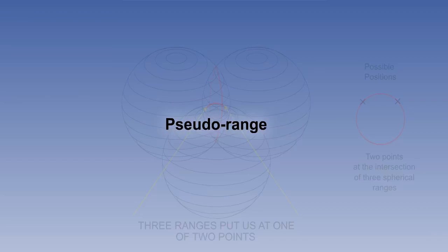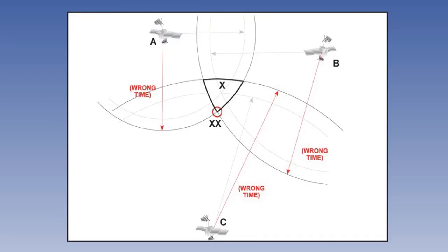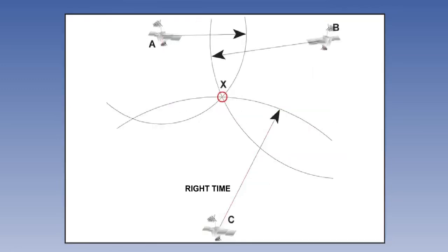This desynchronization, or clock bias, means that the range calculation will be erroneous, which is why it is referred to as a pseudo-range. The receiver clock is deliberately kept in error by a small factor to ensure that the correction process can only go in one direction. As a result, the position lines will not meet in a point, but in a cocked hat. So, when the receiver sets about calculating the correct ranges, it knows that it must reduce the pseudo-ranges.